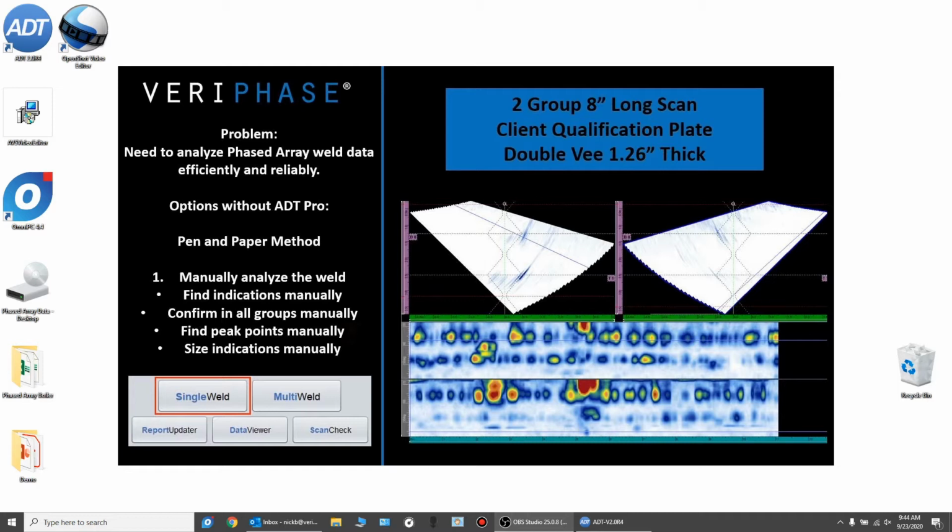Really the real issue with manual analysis when it comes to phased array is it's obviously time consuming. Way too much time gets spent on all the tedious tasks that are required, like moving cursors, trying to find the highest amplitude spot, the 6 dB ends, changing the different displays, manually finding the same indication in every group, and then deciding which one to do the final analysis in.